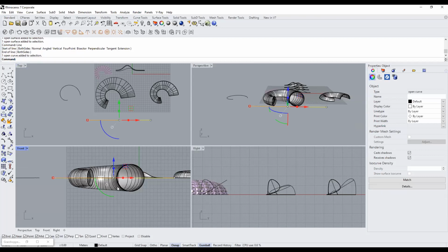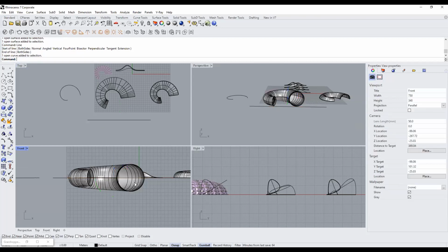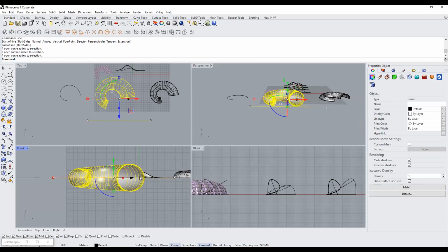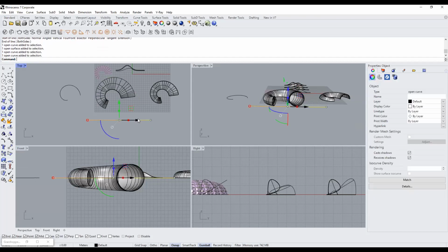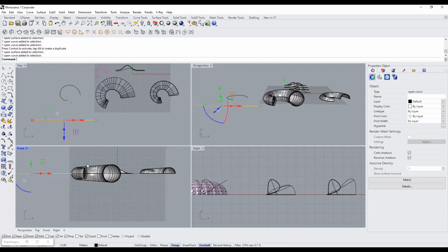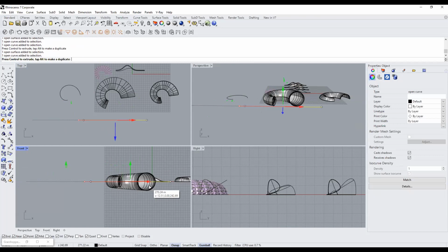After you do that, look at it in the front viewport. Make sure it completely passes through the surface. Like I have the surface and the curve, you can see the curve completely cuts through the surface. It should not be somewhere random like this, where the curve and the surface do not cut in front. Make sure they perfectly cut like how you're seeing on my screen.